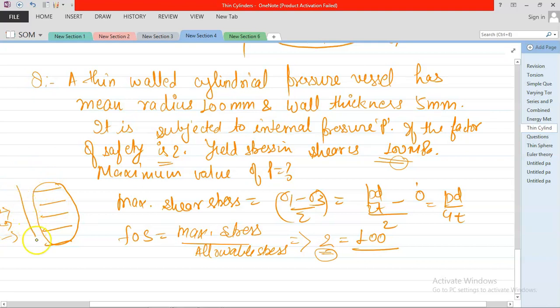But here they make two parallel white strips. Why? This is your allowable range. You can go up to here, but not here. So this is the same with the maximum stress and allowable stress. This is the line that would lead to failure, but this is the line for the warning.